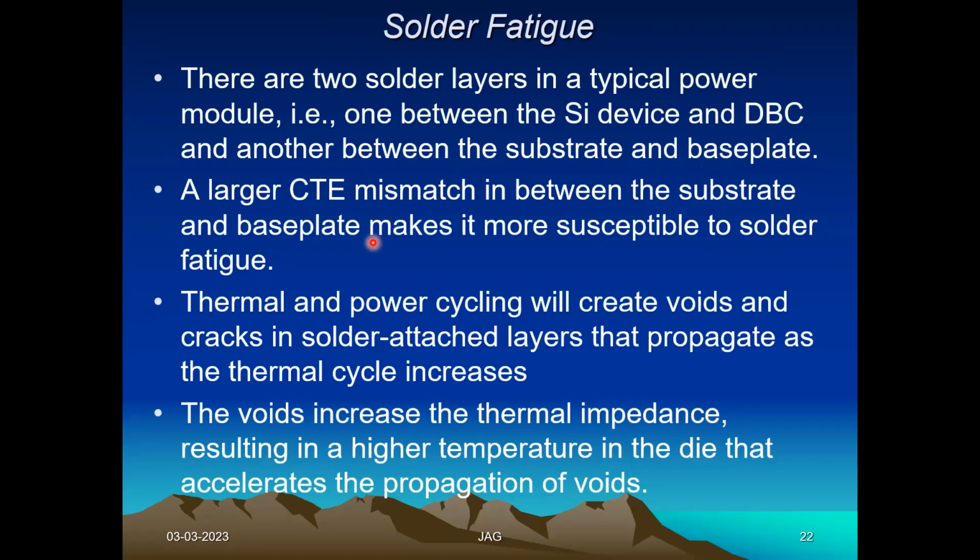Another one: the void increases the thermal impedance. Say a void is created, a gap between two conducting surfaces. Then what will happen? That area will not be available for conduction, so the remaining area will experience a higher density of conduction. Maybe it is temperature, maybe it is current. So the current density will increase, or the temperature density will increase.